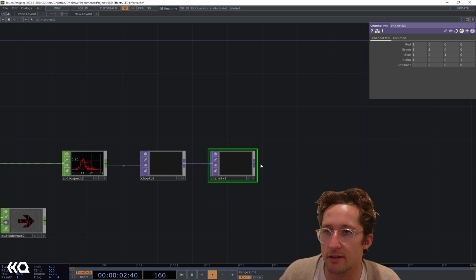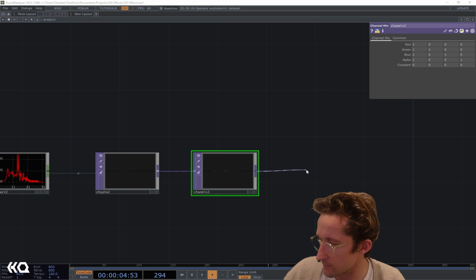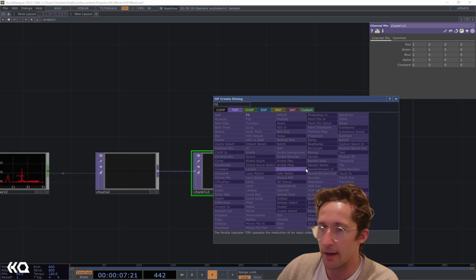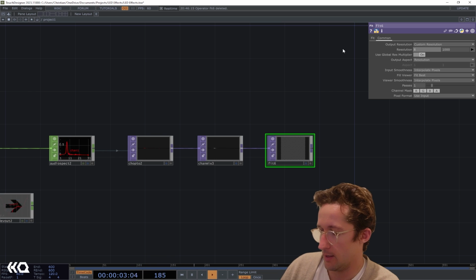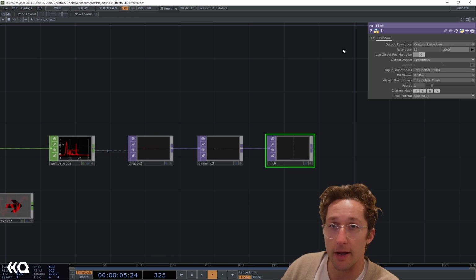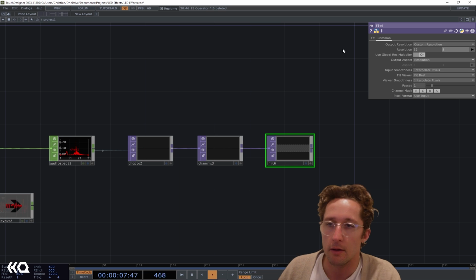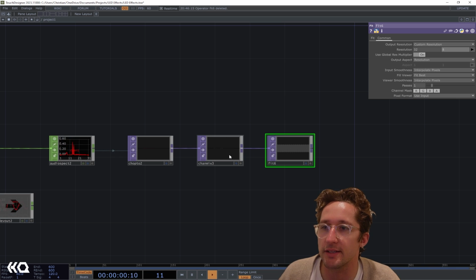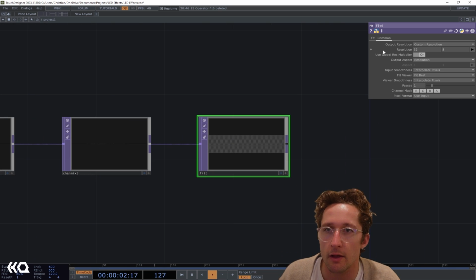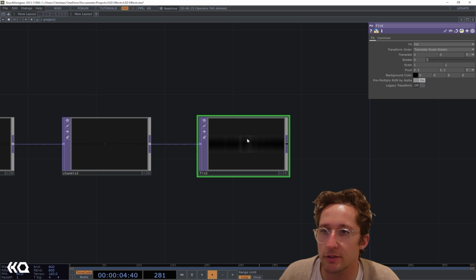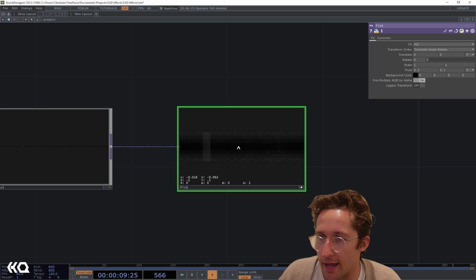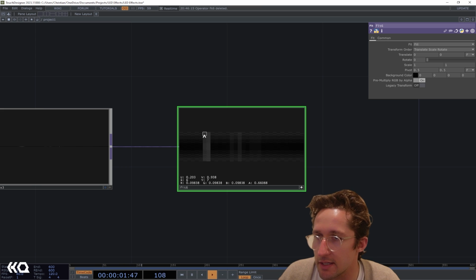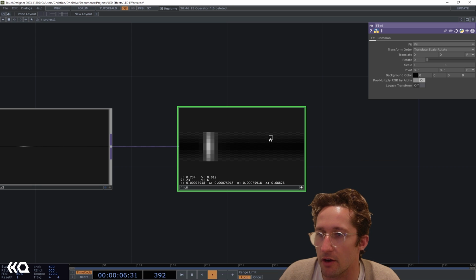So now we see our top is purely white, and we want to fit this. And we're going to make this 32 by 8. This is the wrong orientation, but this is going to more easily let us convert this over. And we're just going to have to flip this after we do it. So we're going to hit this on a fill. And if I press the display active and then I press D over here, we can see the values that we're getting in. And so we're getting a nice fall off from these peaks on the audio spectrum.